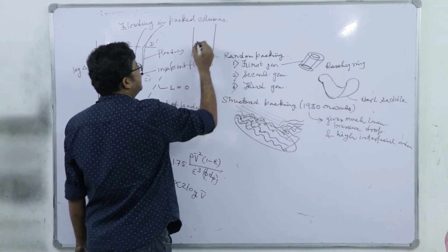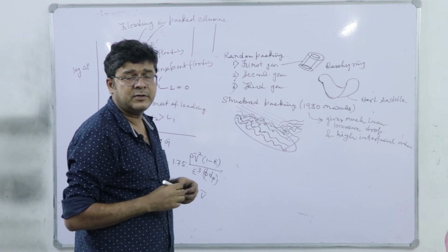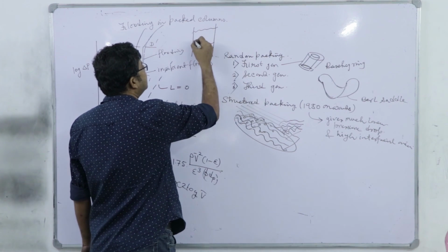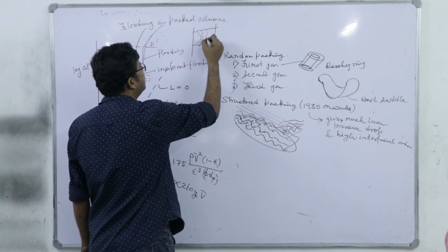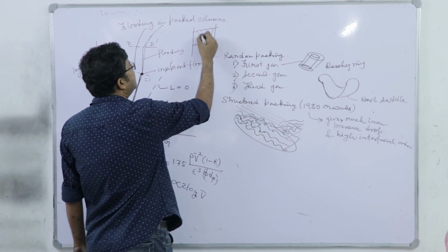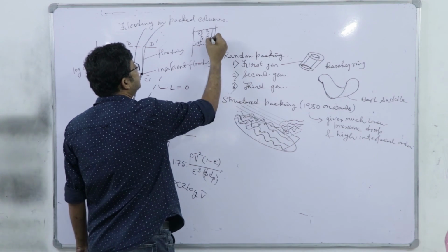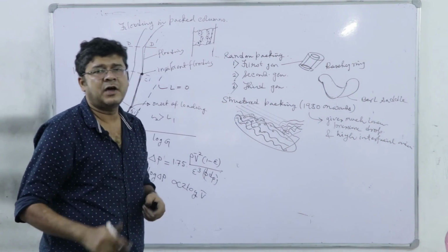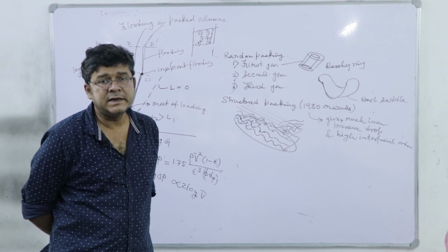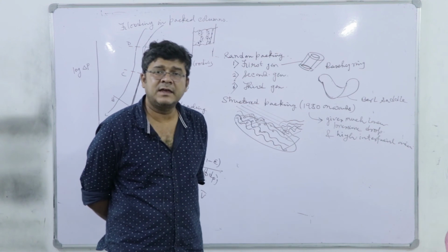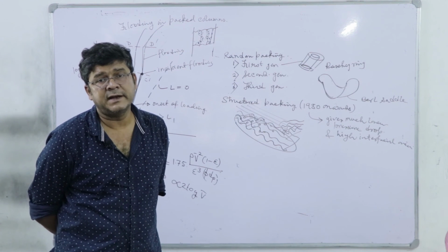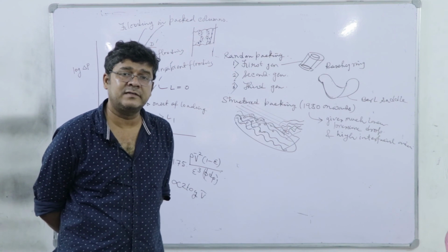And because of that, what happens? In a packed bed we know it is a liquid discontinuous, gas continuous contacting pattern, right. But if the liquid starts accumulating here, the liquid will fill up the space between these pores. The spaces between the packing will be entirely filled up by the liquid, through which the gas will be passing as a discontinuous or dispersed phase, right. So, there will be a tremendous drop of mass transfer efficiency, because the packed bed we intentionally have chosen to increase the mass transfer efficiency, because in that specific case the gas phase has got the controlling resistance. Component A is highly soluble in the liquid. So, gas phase has got the controlling resistance, so gas phase must be continuous.